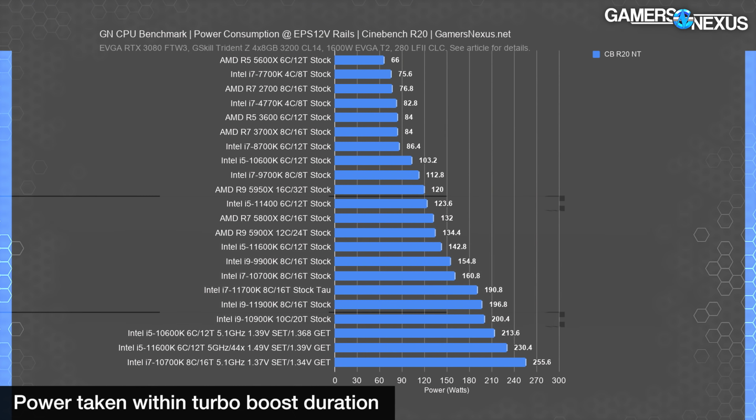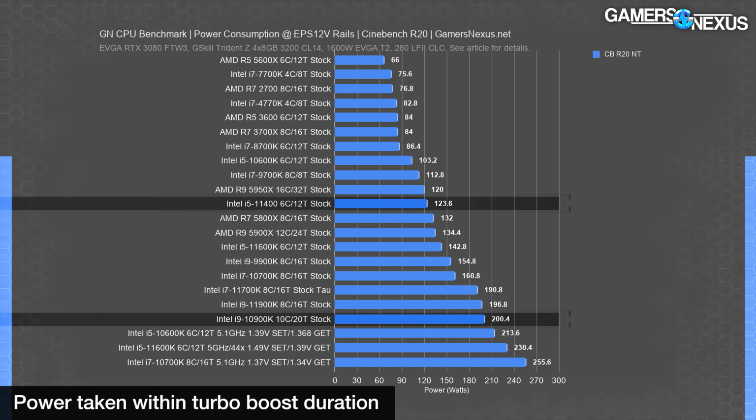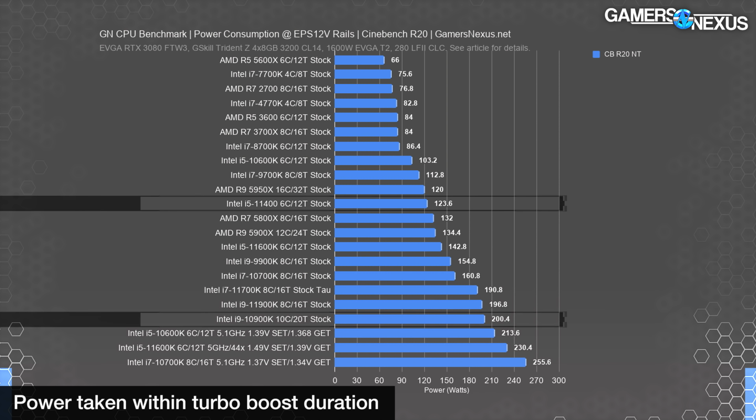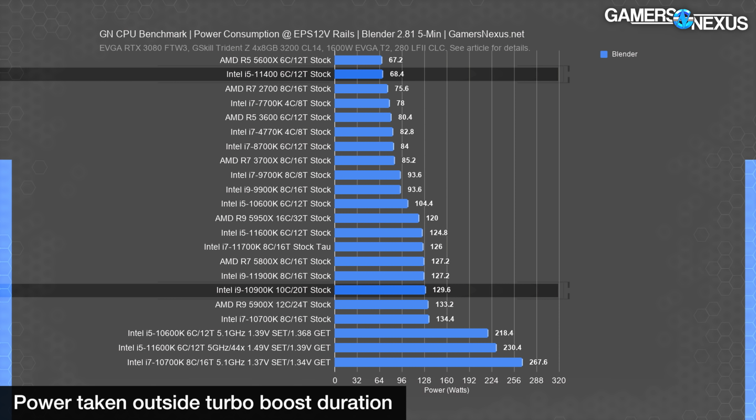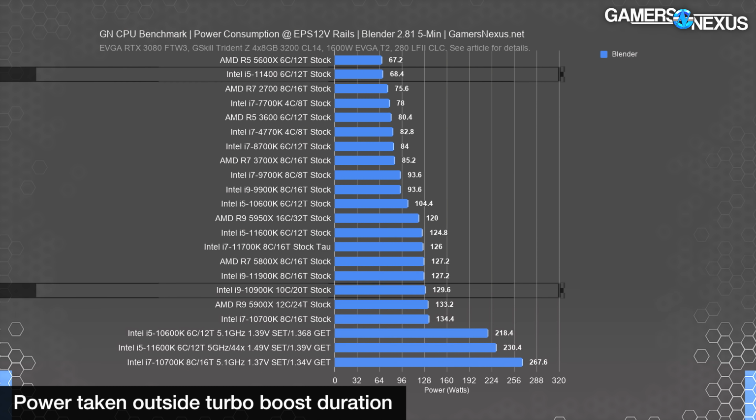Within tau, before the 56 or so second mark, the power consumption can be significantly higher. We're not sure if that's still going to be the case with this one. It probably will. And you might see 75 watts to 100 watts more while it's boosting to its highest possible frequency before it falls off the cliff that it's designed to fall off of and drops down.